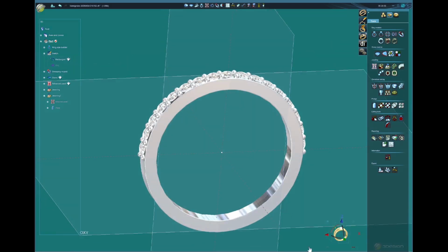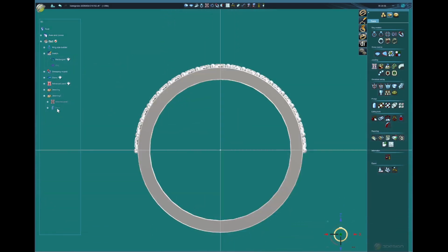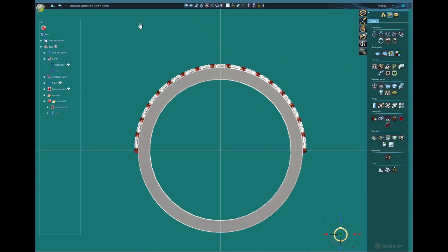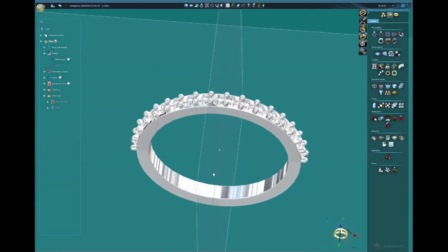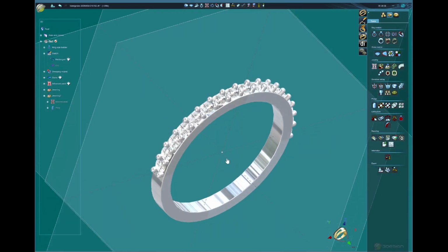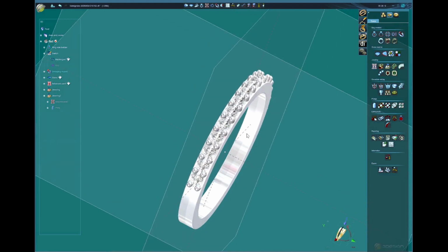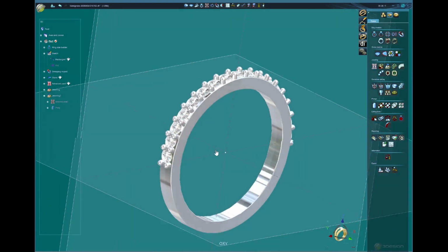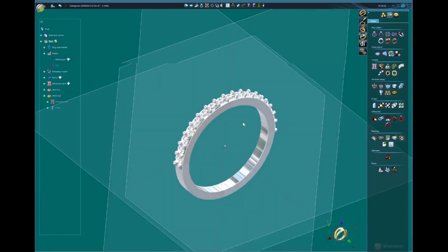So that's why I like to leave, as I told you, minus 0.4, which is going to be plenty for shrinkage and polishing, and the setter is going to be very happy because they will have space to finish and bend the prongs and have a ball. So we're good with that.